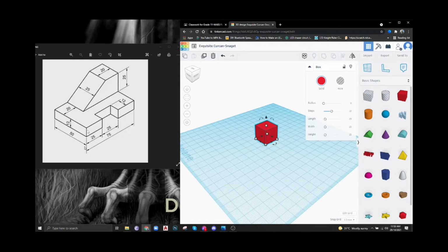First off, we need to apply the dimensions 50, 75 by 12. So in our front, just click this part here, this will show. You can click here and change this to the desired size that you want. You could enter or press tab. When you press tab, it's transferring to the other side of the dimensions, which we will be adding 75.